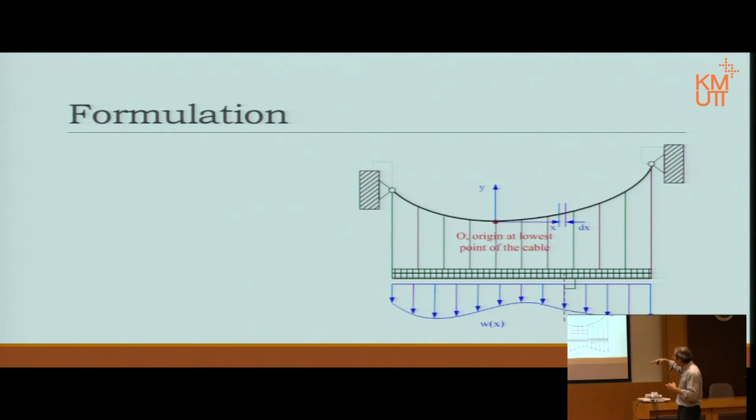By the way, although the load goes through the suspenders, it's assumed to be distributed equally, as if the distributed load is attached to the main cable itself. That is theory. It's not exactly true, but usually there will be some rule saying how far apart the suspenders can be to allow that assumption to be true. But that is again in a higher course.